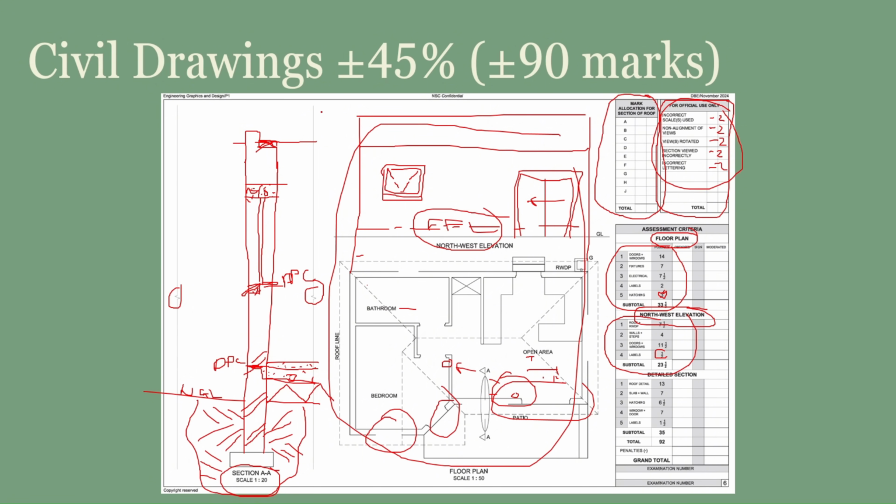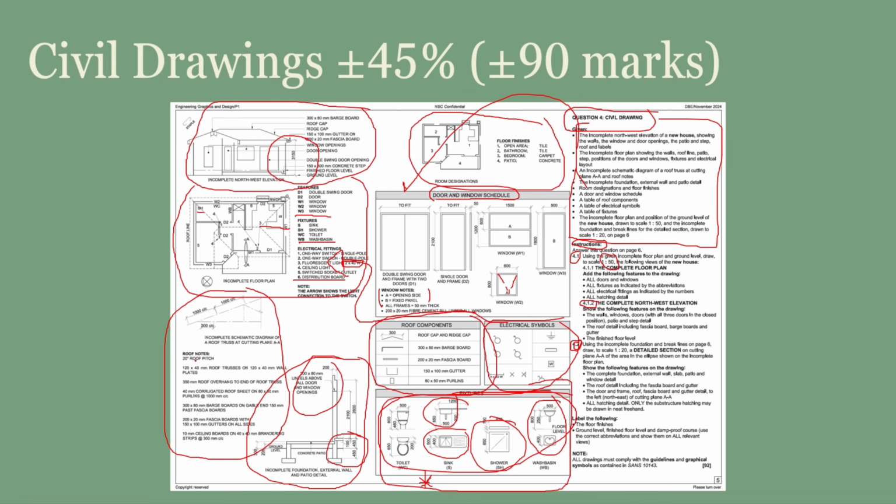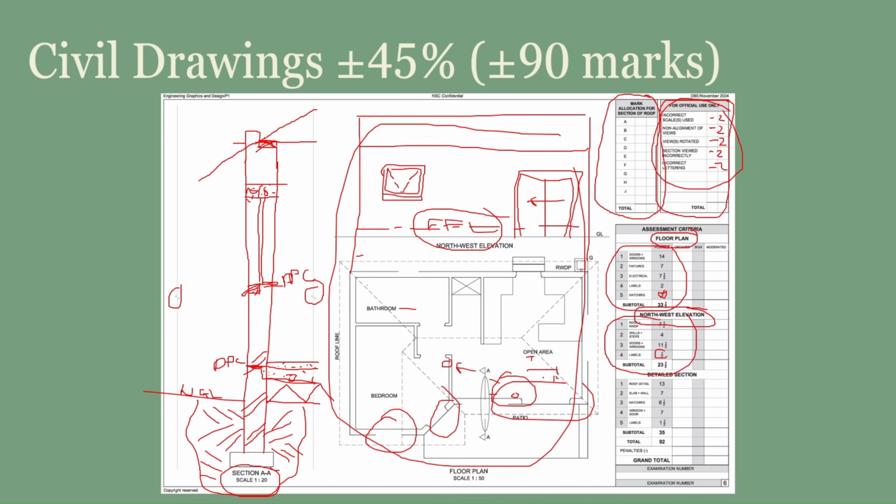In this corner, you're going to apply the specific degrees as given here of the truss, which is a 20 degree. So I will put my protractor here and get 20 degrees. I'll apply the thickness of the truss over there and over there. Put the purlins in, add the ceiling board, and put the purlins here at the top. Add the sheet at the top as specified in the question. And then don't forget to apply the hatching here also in this part of the wall and over here. And sometimes when the sectional view goes into the bathroom, sometimes you will see part of a feature like a toilet or a shower or some sort of sanitary fixture.